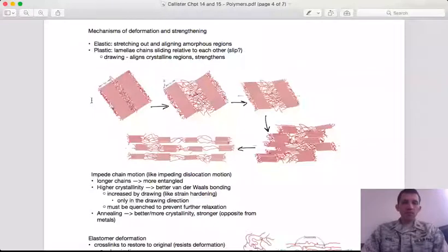If you think about the atomic structure of a polymer system, as we talked about in the last video, especially for straight-chained simple polymers, you have regions of crystalline behavior where the polymer chains are able to lie next to one another densely in a repeating pattern, right, to form a crystal.